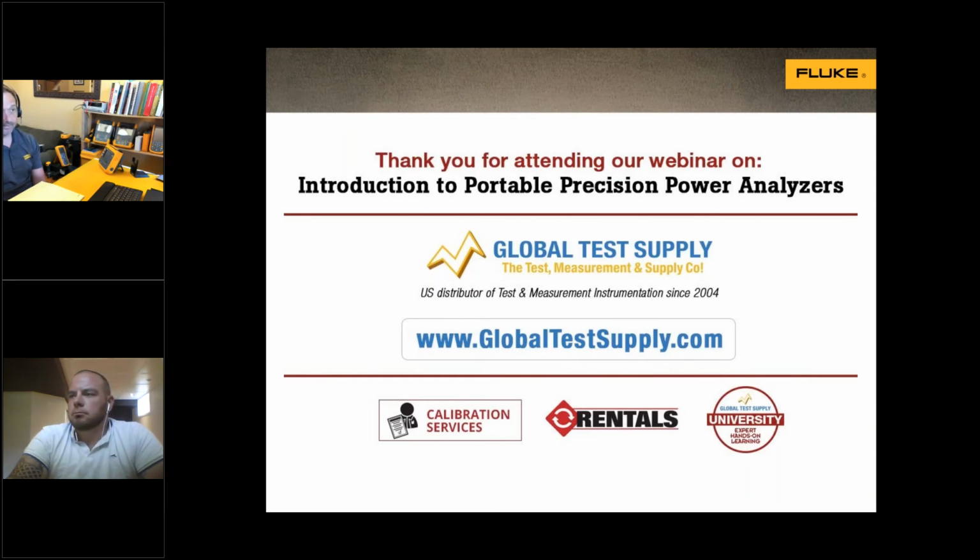The bandwidth capability is always there for making measurements all the way up to 500 kilohertz. If you don't have that kind of range or requirement, but need to go above 50 or 60 hertz, Fluke does also make a power quality tool, the 437, which does 400 hertz also, if that's in the range of what you're making your measurements in, like for naval or aircraft applications. But certainly the Norma could do that also.